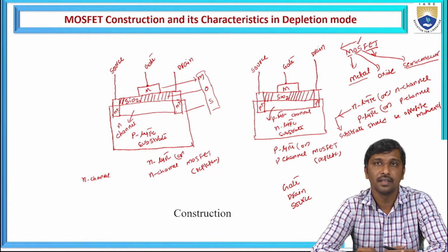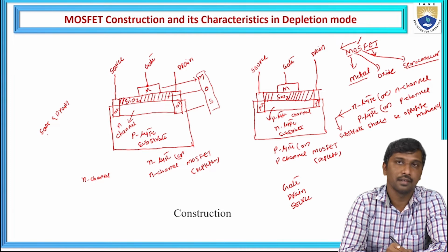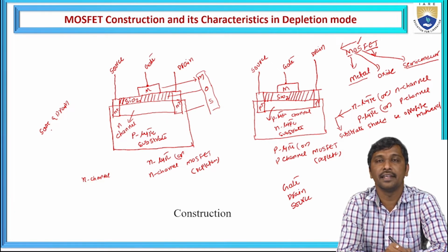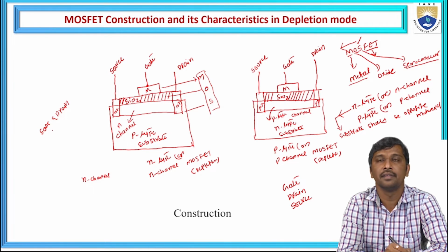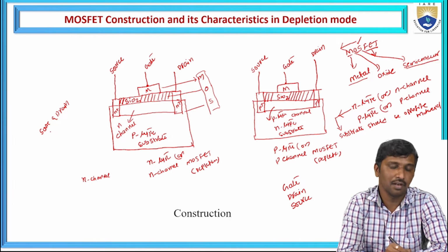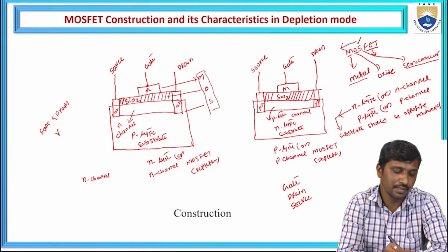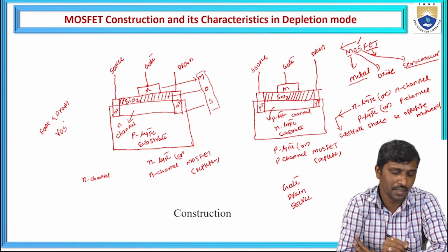That is the reason we need to apply a biasing voltage between the source and drain. In between these two terminals, we need to identify how much potential difference will be observed when we are applying the biasing, or an electric field, between the source and the drain. And that is represented as VDS, drain to source voltage.